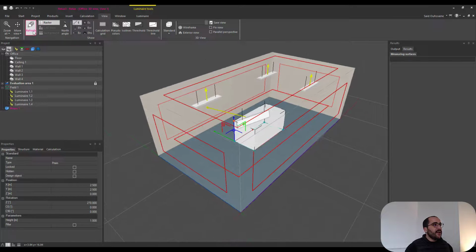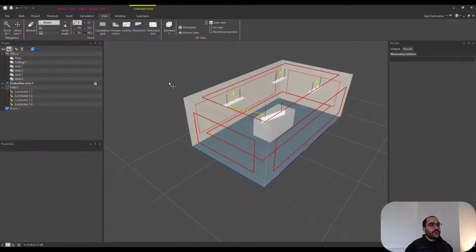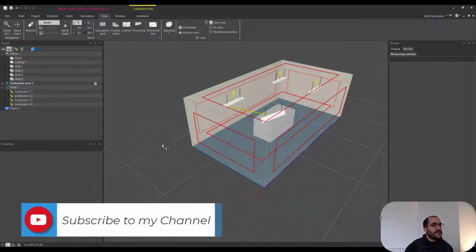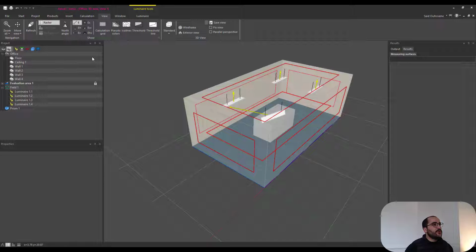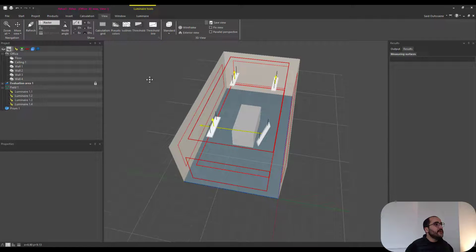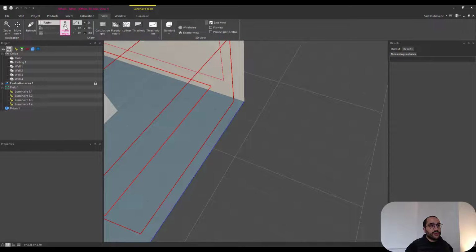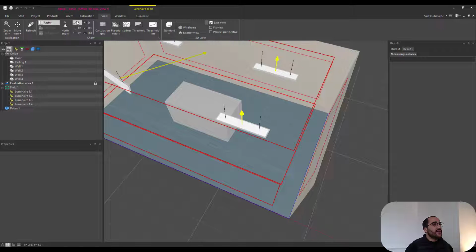And then there is rectangular selection. You cannot rotate your project. You will be selecting instead when you want to do the same thing, to rotate. And then there is the raster. It's this one here. You can hide it or show it. There's also the CAD plan and the background image if you have them in your project. Let's go back to our rotate here. And then there is the north angle. It's here. You can hide it or show it. Let's hide it.